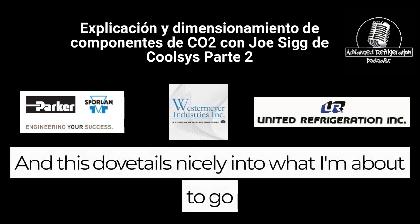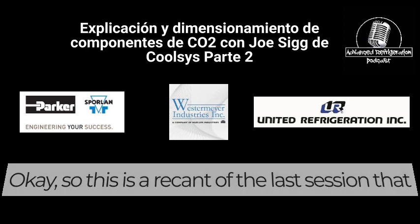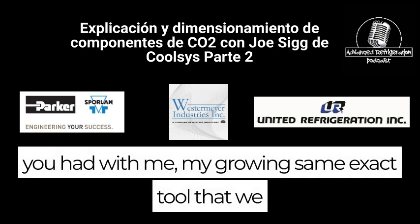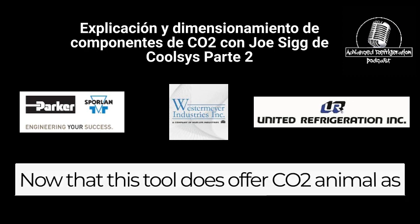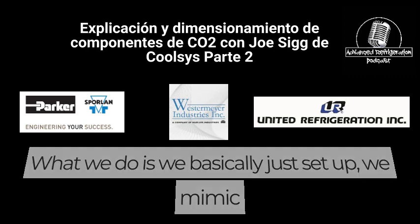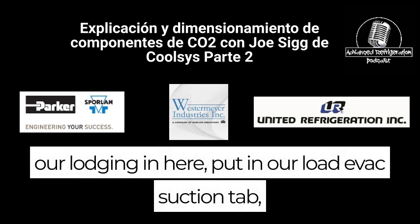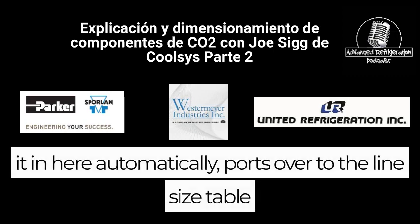Okay. And this dovetails nicely into what I'm about to go into, which is the line sizing for CO2 systems. This is a recap of the last session that you had with me. I brought up the same exact tool that we had open last time. You'll see this tool does offer CO2 and ammonia, as well as some other fancy refrigerants that we use. We mimic our legend in here, put in our load, evaporator suction temp, room temp, and any valve pressure drop. It automatically ports over to the line size table.